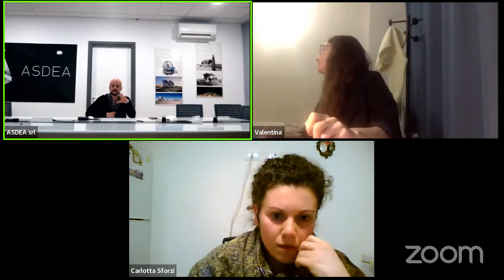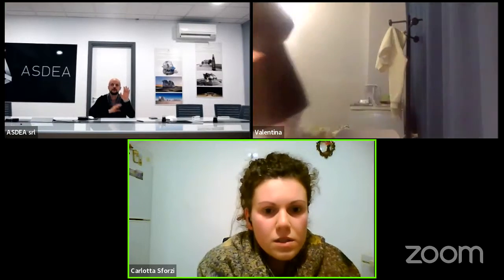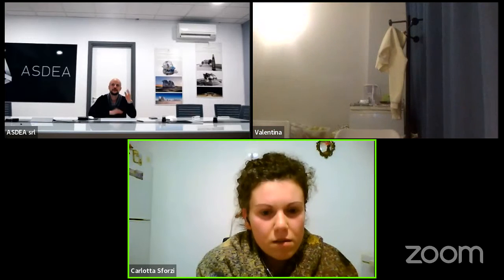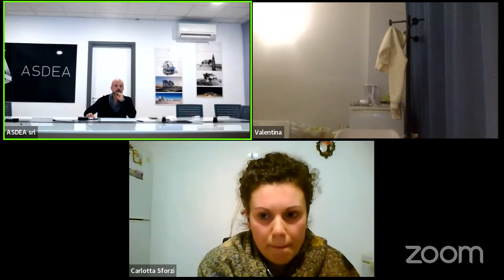Actually, it is the same in terms of the total force that you apply. First of all, you have to pay attention whether you're using standard solid elements for soils or UP elements, because there is a difference. You can use standard displacement based elements. Because in standard elements, there is an option. Let me share my screen so you can see it, because sometimes people have made this mistake.